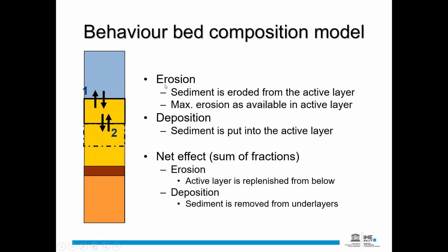If we are talking about erosion, then the sediment is eroded from the active layer and goes into the water. And the maximum erosion in one time step is the amount of sediment which is available in this active layer. But if we are in deposition mode, then the sediment comes from the water column into the active layer and deposits there. You can have different fractions of sediments, of course, mixed into this active layer, and the net effect is the sum of fractions.